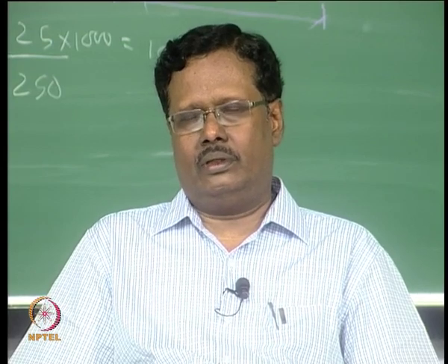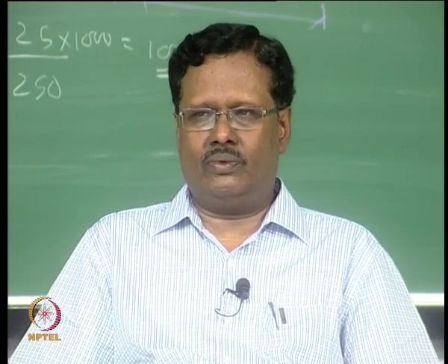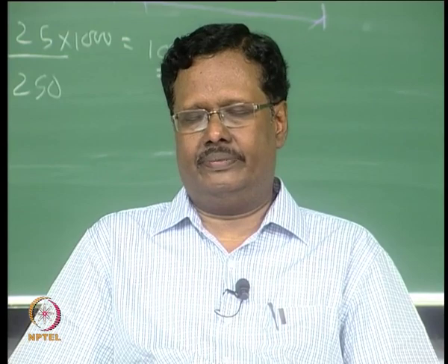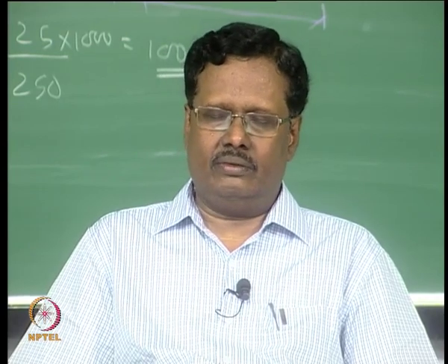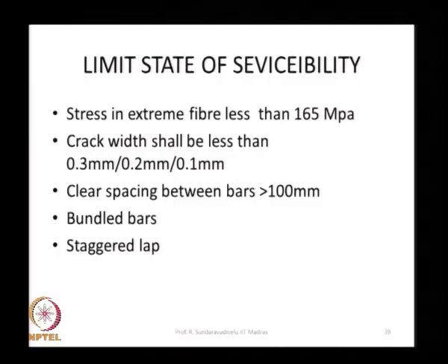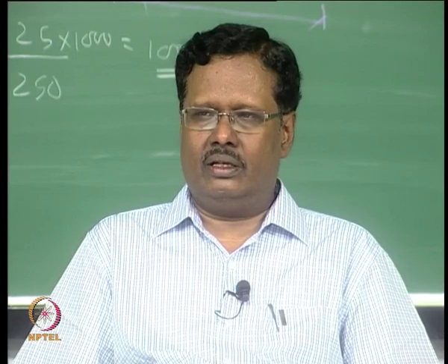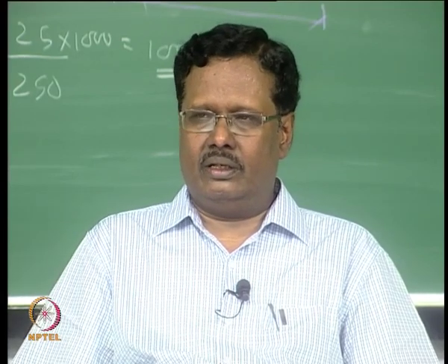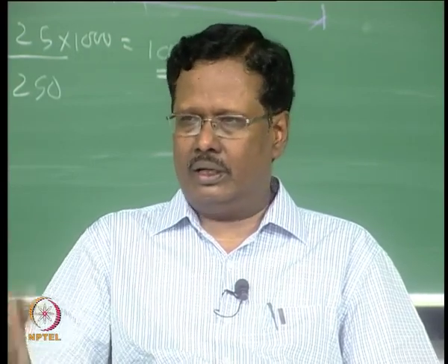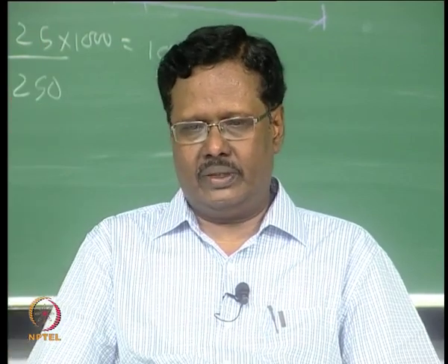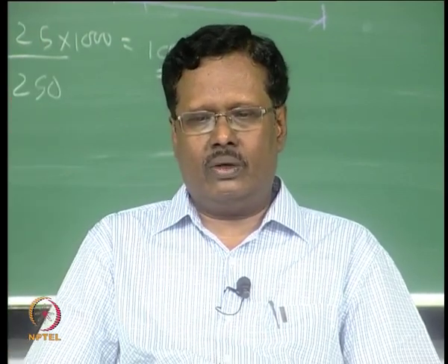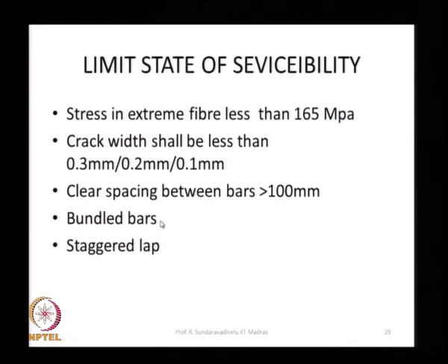20 mm generally, sometimes they use 40 mm for plain concrete for foundations. 20 mm means the aggregate has to go, the distance should be more than 20 millimeter. Since we are doing it under water as well as below the seabed, minus 25 and all, the concrete has to go from the top. So, we need a spacing of greater than 100 mm. To achieve this we can use the bundled bars.